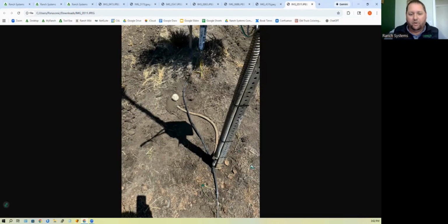Also, a small thing to note is the transducer. This is another item that gets abused in standard farming practices. It gets pulled on, drip gets pulled on, especially with our mechanical harvesting equipment. There are brushes, blowers, and things like that that go through here. Sticks drag in this row and damage occurs. A well-secured and protected pressure transducer is in your best interest to get accurate data and reduce damage.